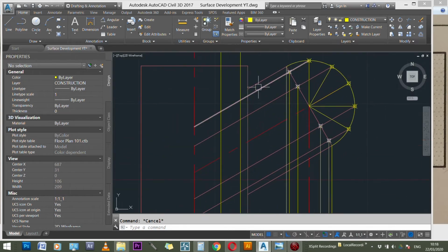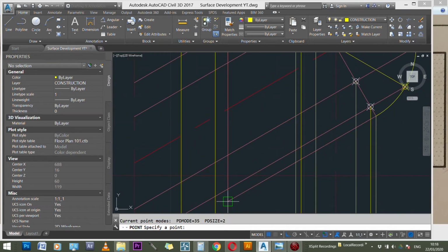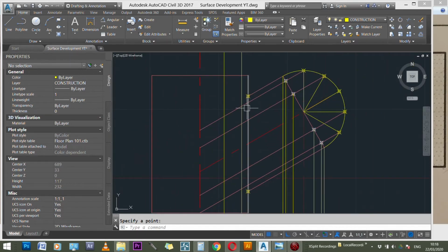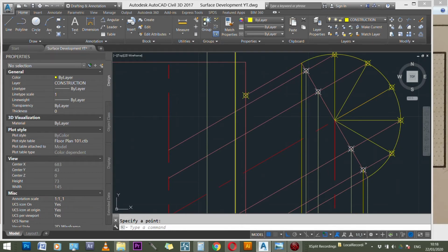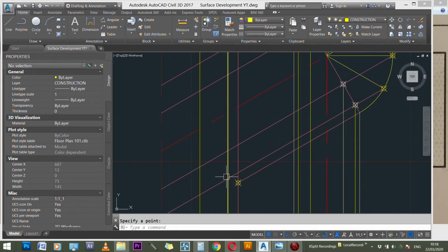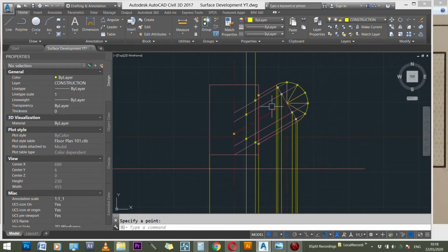So let's go ahead and start solving this POI, point of intersection, and let's put in points as to where I'm going to be drawing my spline. So the first thing is, this is the edge, where the edge meets the edge, so we can just put in these 2 edge points. That's the first thing. And then the second thing is we can come in slowly. So once we have the edge, we then go in 1 step, right there, 1 step, 1 step. Then we're going to go in again, 1 step, 1 step. And then we go all the way to the center. So that is the formula for creating our intersecting path.